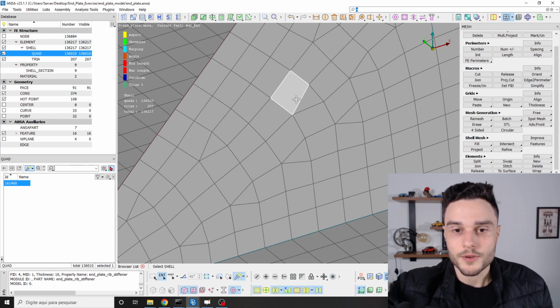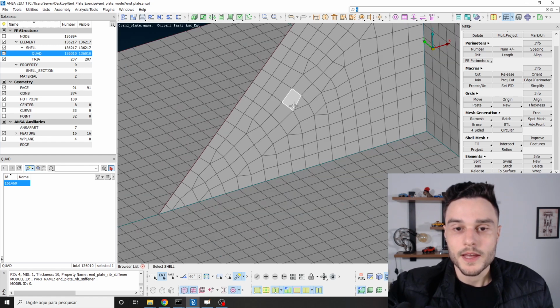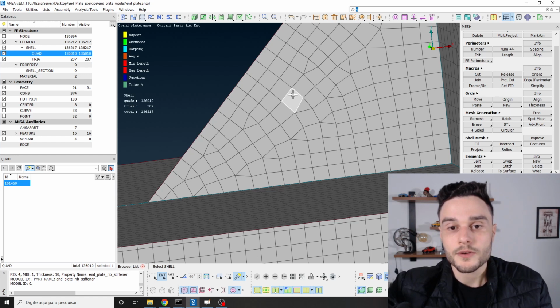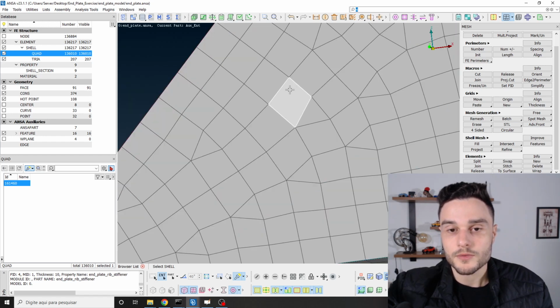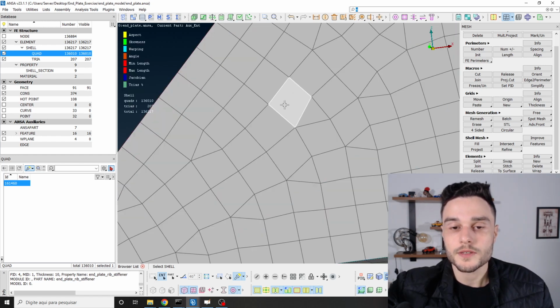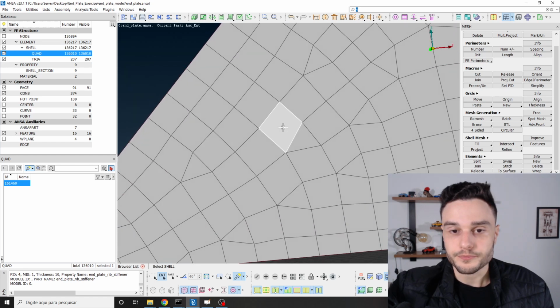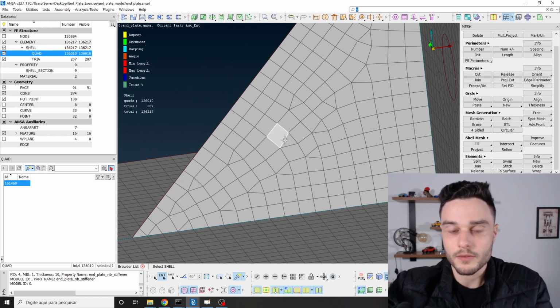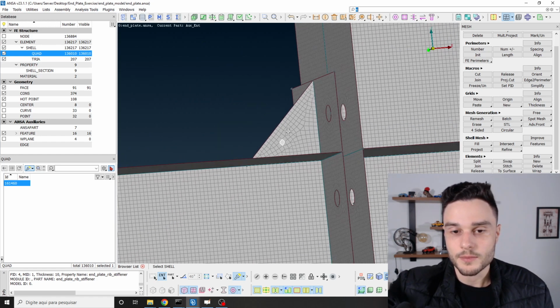And we have 4 integration points in this case to characterize a fully integrated element. And remember that I'm talking about the Gaussian quadrature procedure that is used as a numerical integration procedure to calculate the stiffness matrix of the element. And we need to use integration points in this numerical integration procedure, which is the Gaussian quadrature procedure. Okay? And then when we have a fully integrated element, we have some specific characteristics assigned to this element, as we know.